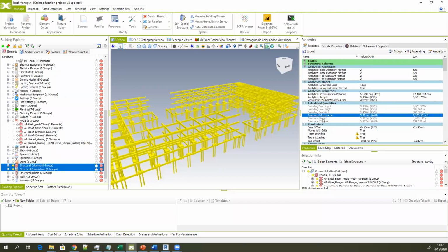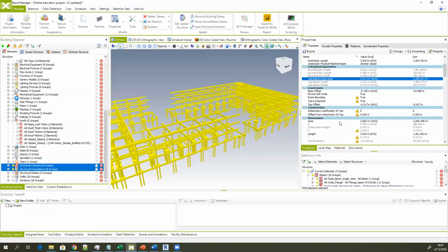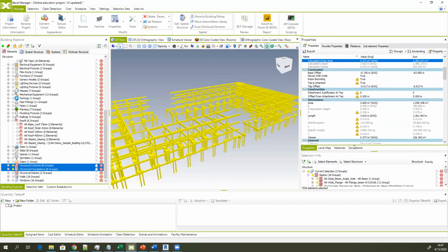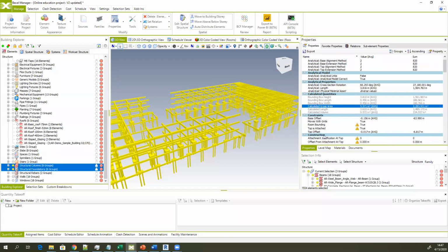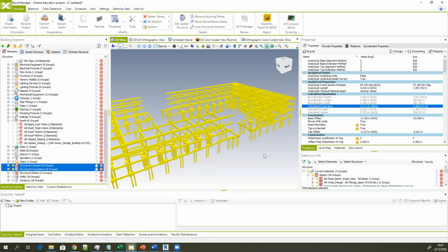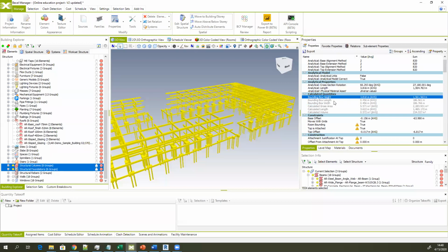And this is something that can help you, but we always recommend you use the values coming from the authoring tools. But sometimes, if you're using some messy or generic BIM model elements which don't have accurate information, or if your authoring tool does not provide the quantities, then you can use calculated quantities, which BEXEL Manager provides for you.